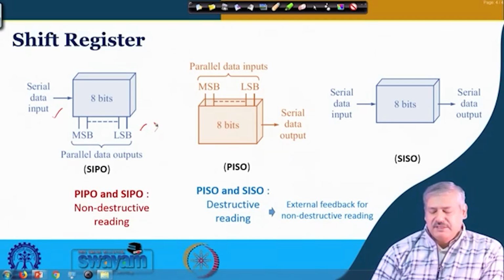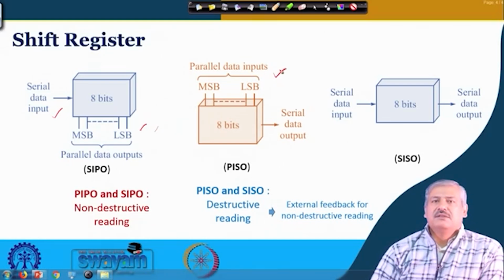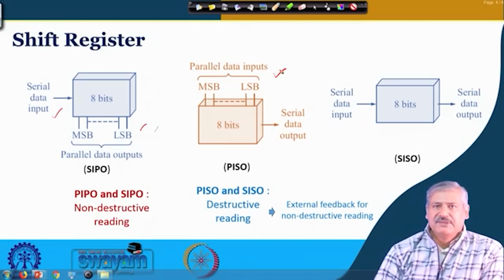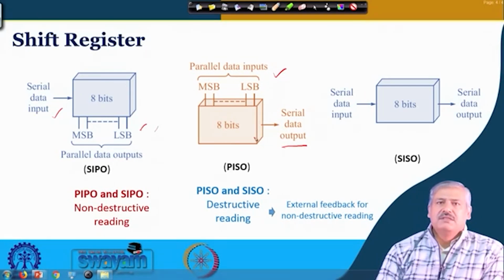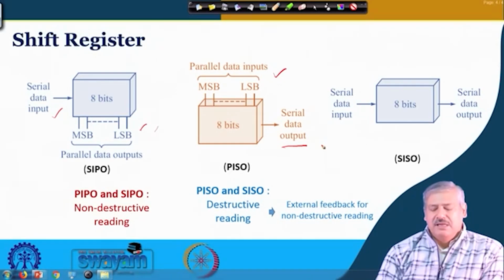The other type is where data is sent to the register parallelly. In one clock cycle all the data gets loaded, unlike the previous case. And then for the reading part, the first data that is in the inmost flip flop is available, and then if it is 8 bits, you need another 7 cycles to push data out of the flip flop.